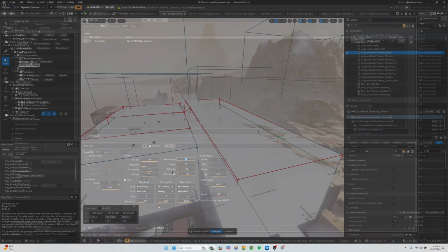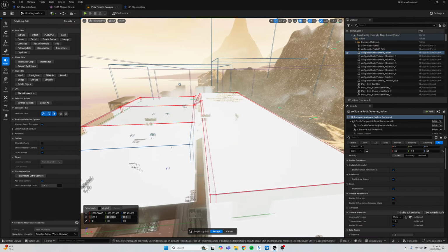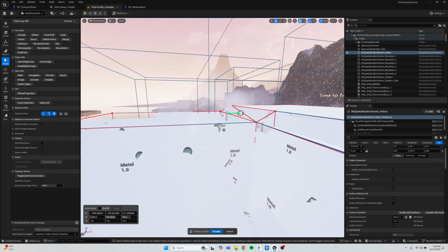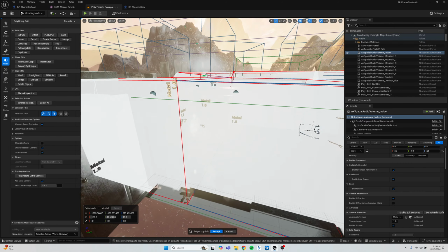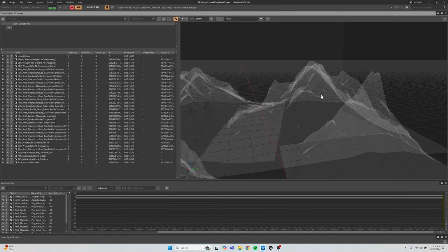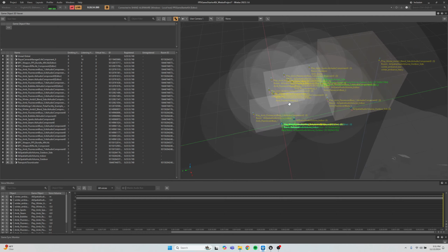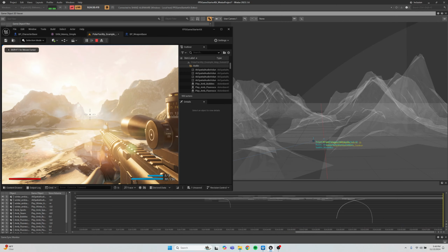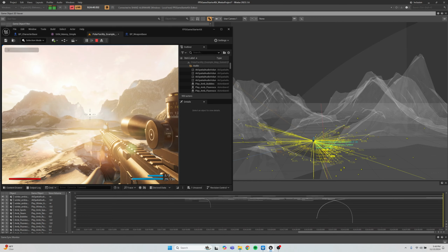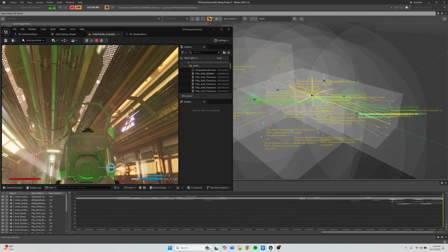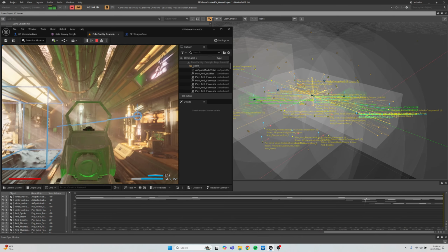For dynamic early reflections, I used the Wwise Reflect plugin along with AK Spatial Audio Volumes and AK Geometry components to convert all scene and mesh data into spatial audio geometry. By setting up and configuring AK Spatial Audio Volume actors in Unreal, I was able to generate reflections that dynamically adjust to the geometry of the space, making each environment feel acoustically accurate.